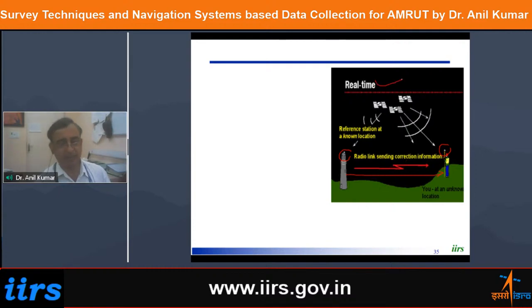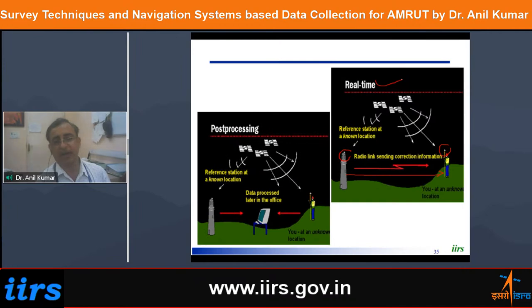But if this application is not required, we can go for post processing. That means the base is working the whole day, the rover is working the whole day. In the evening, we can download the data to a PC or laptop, use post processing software, and apply the corrections from base to rover.